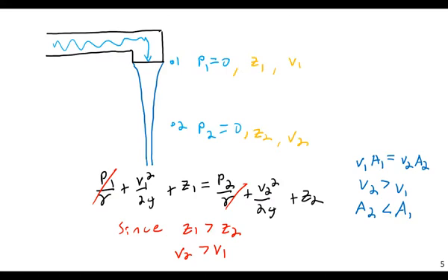This is a very simple application of Bernoulli's equation and the continuity of flow. The pressure is going to be the same here and here. It has to be. Everything's at air pressure. But velocity also has to increase, or actually I should say, even if velocity doesn't increase, gravitational potential energy has to decrease. It's falling water. The gravitational potential energy is decreasing from here to here. That energy has to go somewhere. It can't just disappear into the void. And so where it goes is into giving the fluid greater velocity.